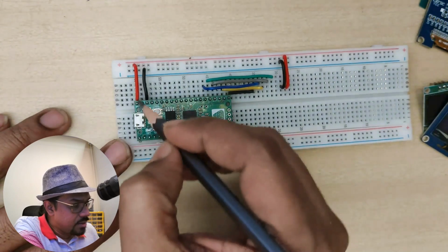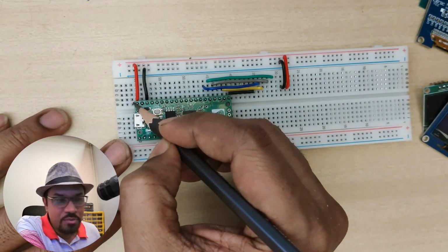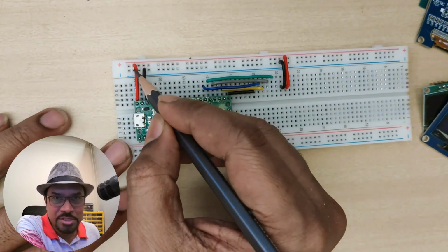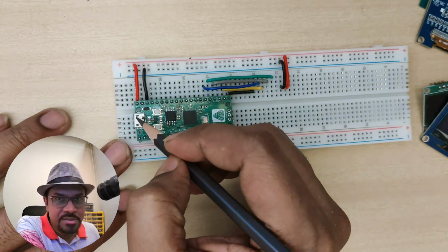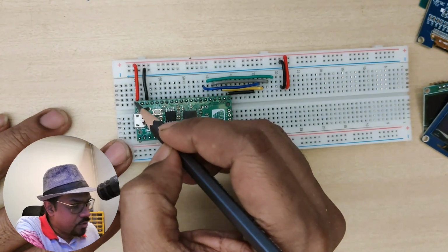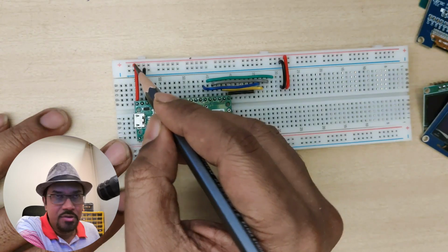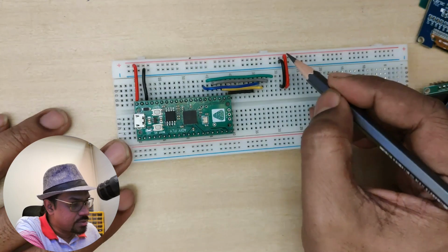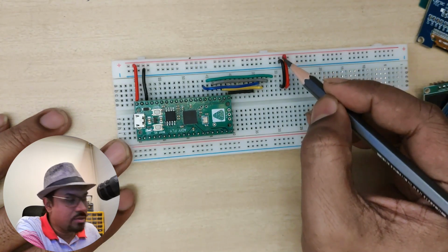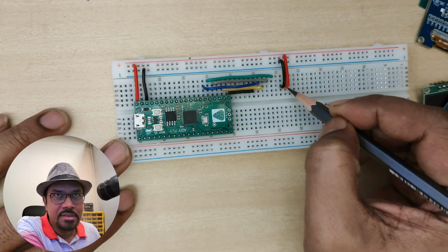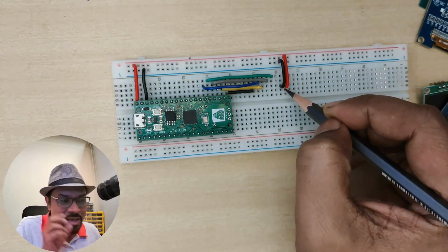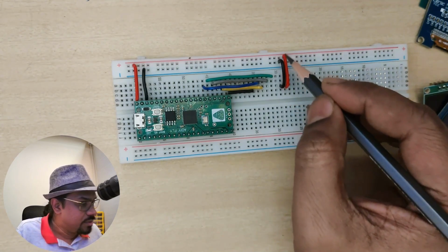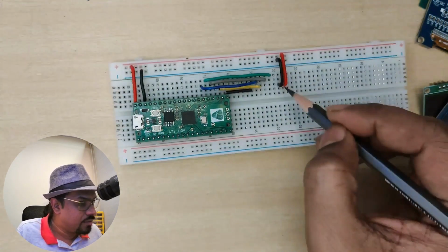Now here's the thing. This pin 40, if you look up from the pin out diagram, is supposed to be the VBus pin, which connects to the micro USB's positive supply voltage. So I have run a wire from here to the positive rail of the breadboard such that you can also see another red wire here connected on this rail to this side. This is where the VCC would go when I connect the display in a while. I'll do that in a while, just hang in there. So this positive rail is actually connected from here all the way till here.